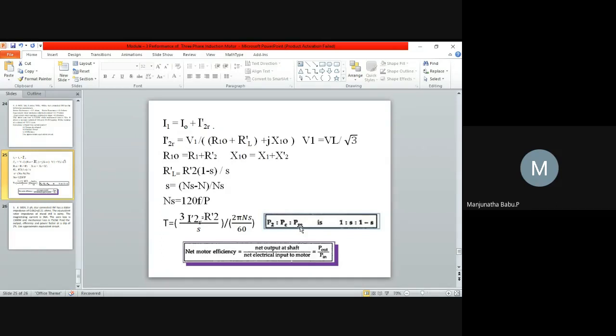So now the total losses will be equal to 1250 plus 1811.6 plus the mechanical loss 1000. So total loss will be equal to 4061.6 watts. So now find efficiency. Efficiency is equal to output power by input power. Input power is already given as 40 kilowatts. Or you can go for P out divided by P out plus total losses.